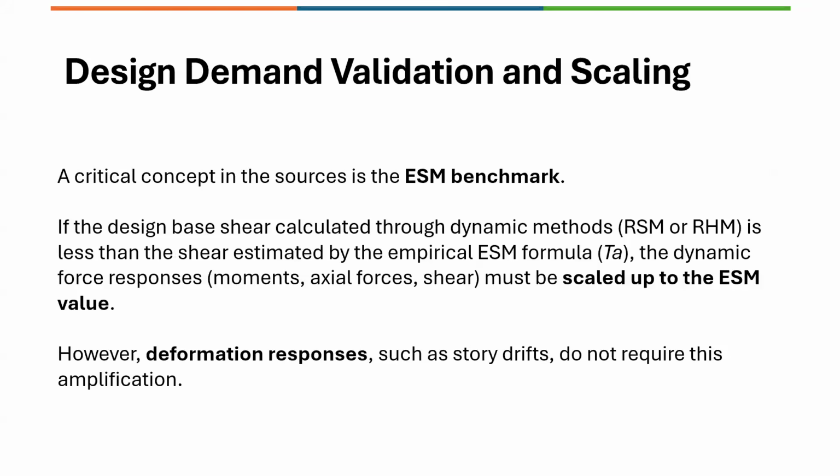And then the ESM will be the benchmark, that is the minimum base shear. In case the dynamic base shears are lesser than this, then those base shears need to be enhanced for this ESM base shear. This is similar to the previous code, and deformation responses need not be amplified. So these are the important things that we need to consider when you're using the respective type of analysis method.